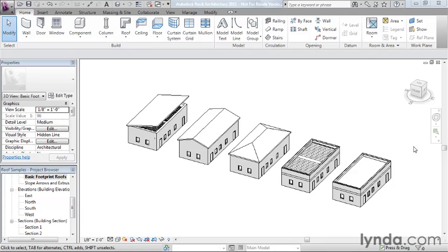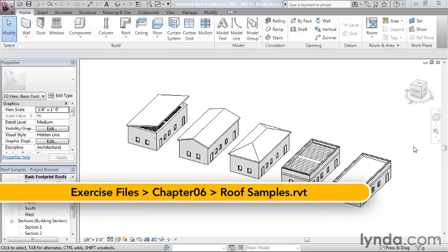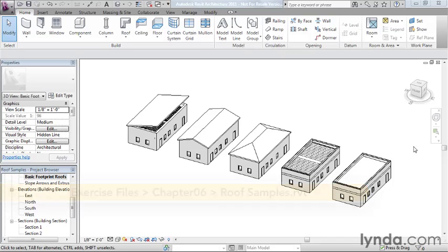As you sketch elements like roofs and floors, the geometry you create will often maintain associative relationships to the surrounding geometry. For example, if you use the Pick Walls option to create your sketch lines, the shape of your roof or floor will change automatically if the walls move. This is only one example. There are other modifications that we can employ to create intelligent relationships among the various parts of our model.